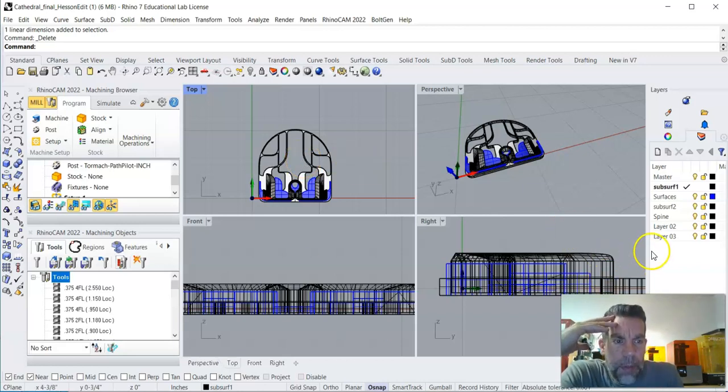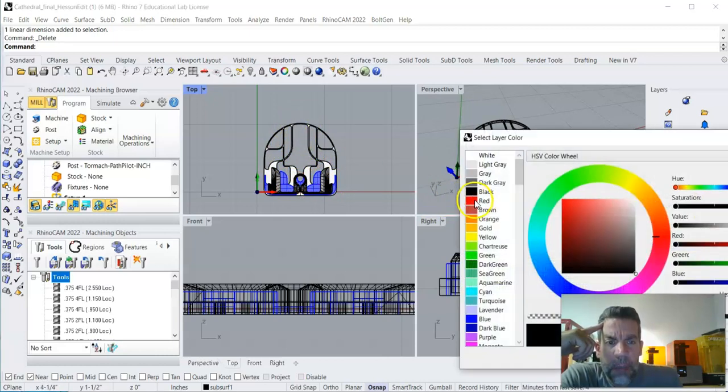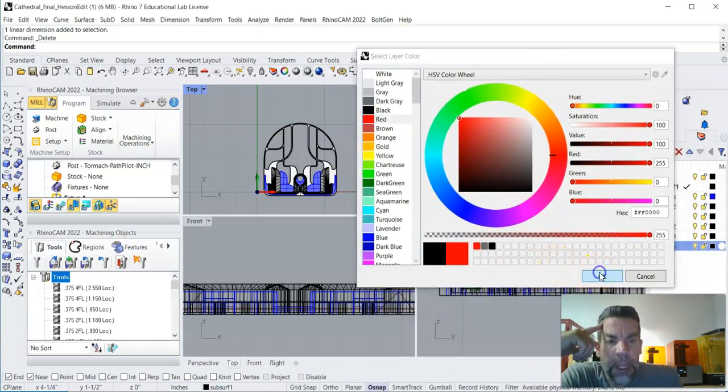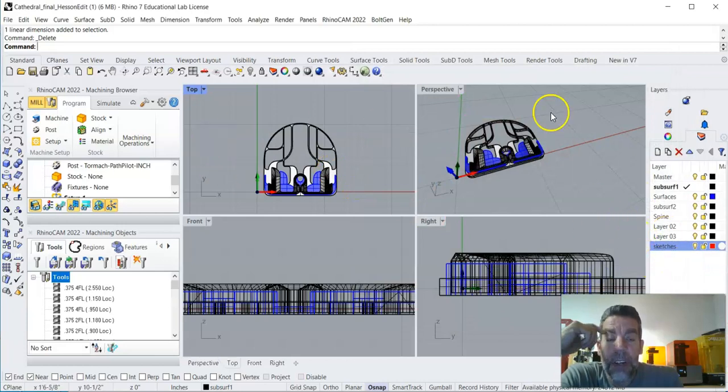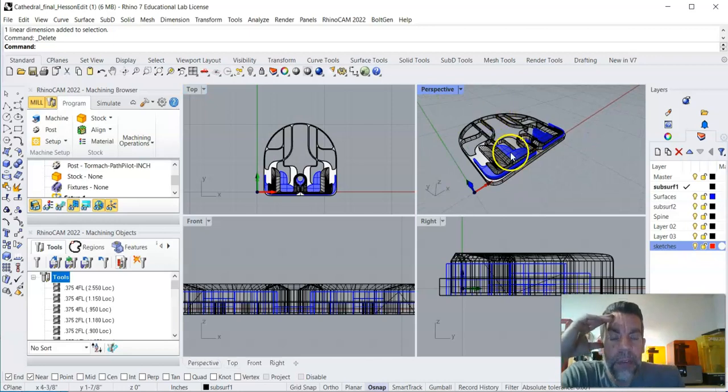Now I'm going to make a new layer over here, just for me to make some sketches off of your file, because for 2D milling operations like what I was telling you about with the stained glass effect, or these window effects that you're getting here, you really don't need any 3D geometry if that's what we're doing. So I'm just going to make a sketch layer, so it'll make it easier later on when we're generating milling tool paths. We can select geometry pretty easily.